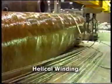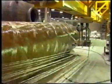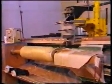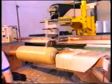In helical winding, material is deposited in a helical path in one direction, then turns around on end and returns in a helical path in the opposite direction. This routine continues until part thickness has been built up. To provide the desired mechanical properties of a part, combinations of hoop and helical winding can also be performed.